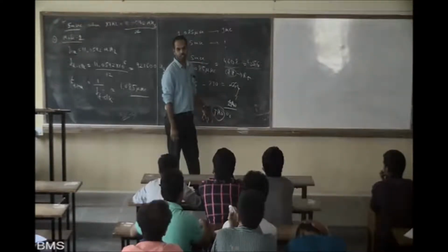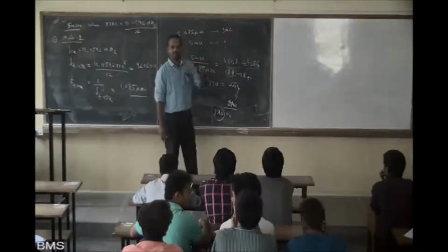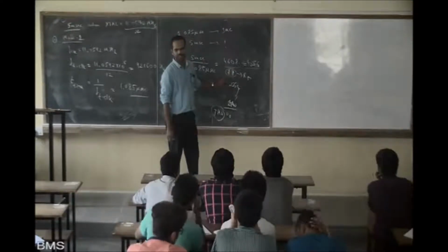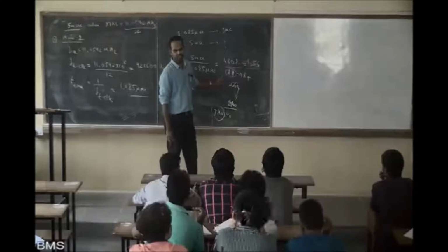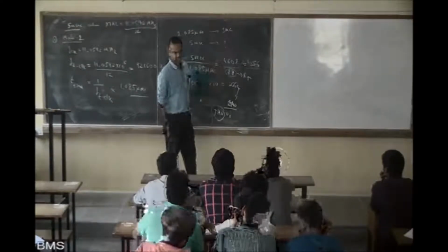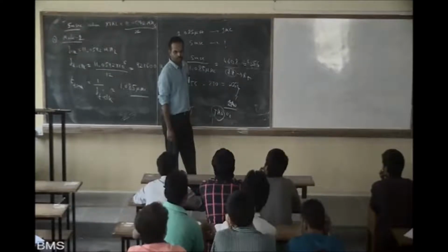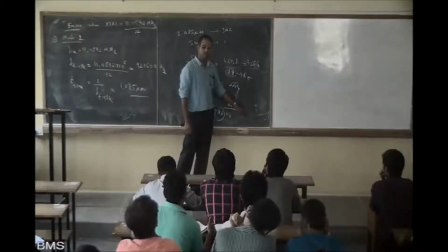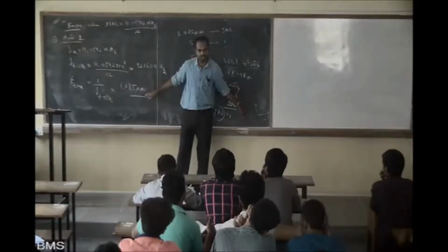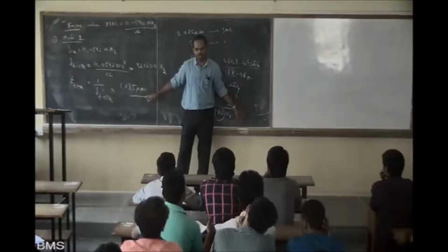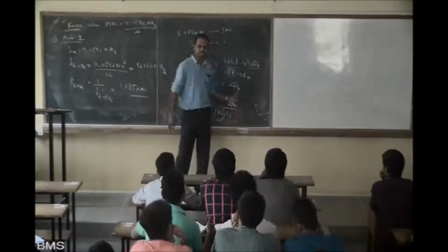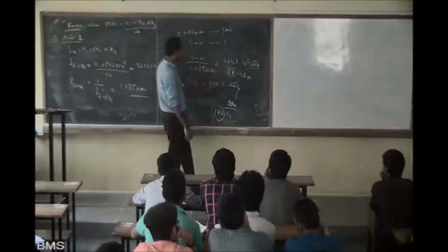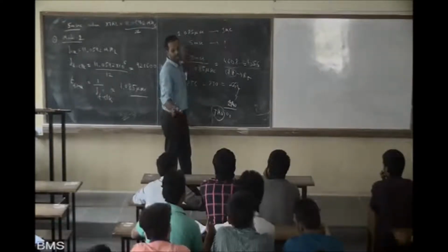Anything above 18 is right. Below 18 is wrong. You're getting my point? Anything above 18. We'll come to that, like what exactly mode 2 does, we'll discuss. 5 milliseconds. It will start from 0 to FF. What will be the time delay if this is given? 1.085 microsecond into 256. That is the minimum time delay generated. Multiply by 18, it should be a value around 5 milliseconds. You will not get the exact time delay.